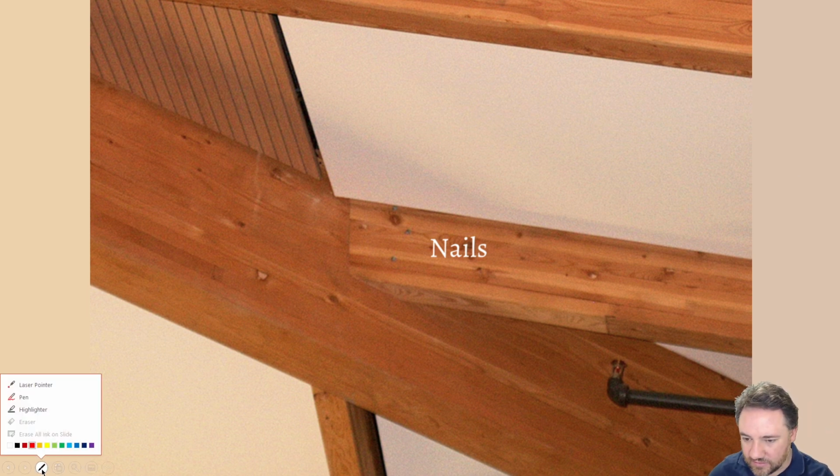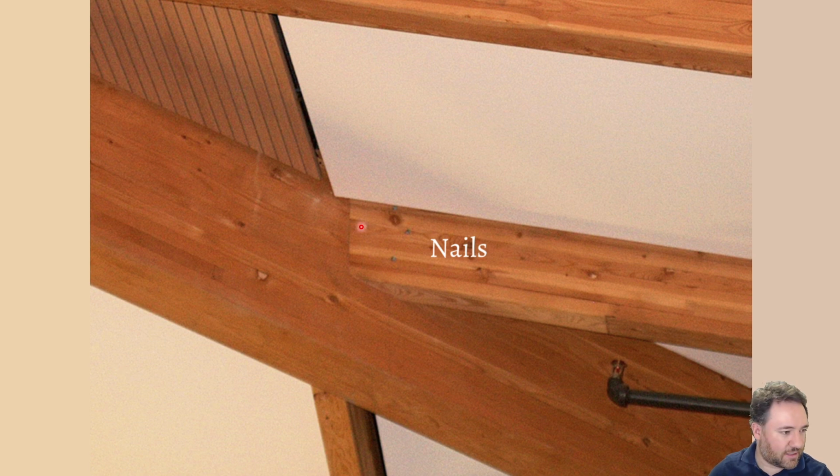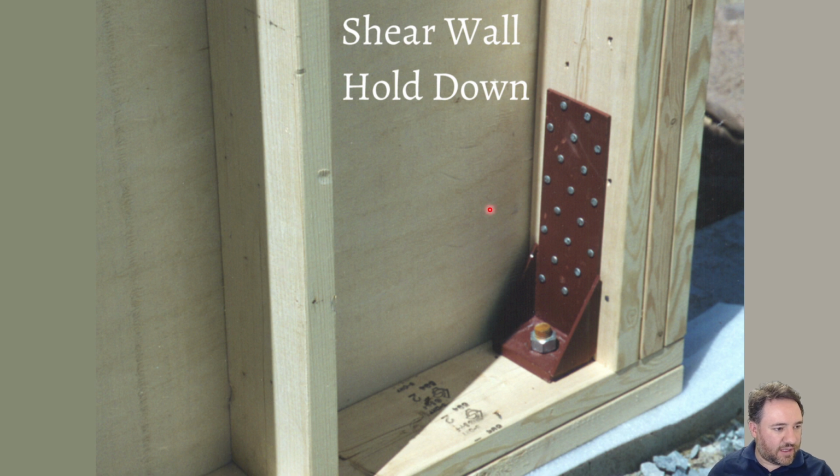Bring up my pointer. You can see some nails right here that are holding this kind of purlin or something to this larger beam. And as we mentioned before, if we have quite a lot of force that we need to resist, for example, in this case of this pretty heavy duty hold down that's at the outside of a light frame shear wall, we can just use a lot of nails and lay them out in a matrix pattern. This is an easy way to connect a steel plate to a timber member, as long as we're loading it in shear like this.